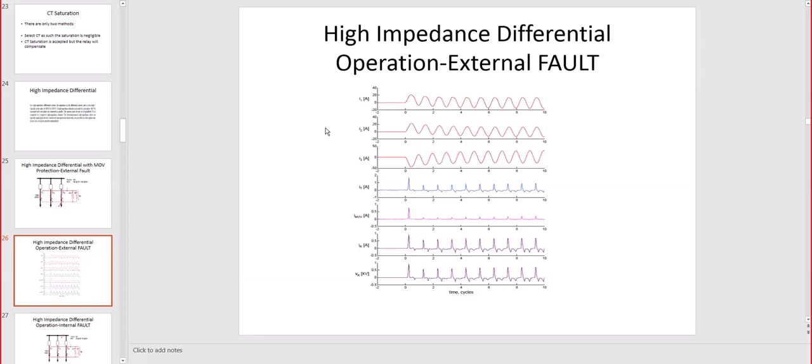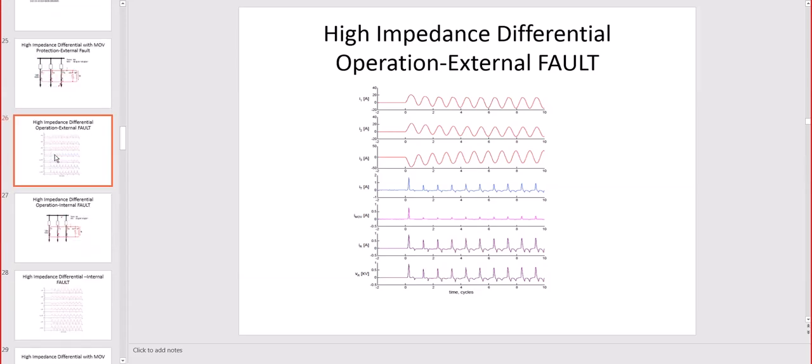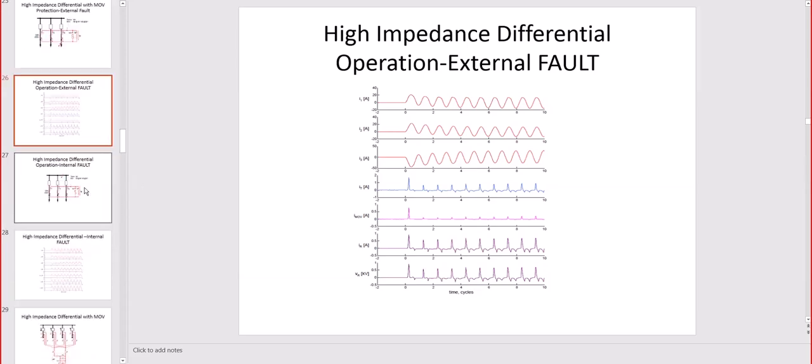Harmonics 3I0 is what interests us, and those are multiple of 3, and yes, they are composed by harmonic 3 and multiple of 3, like 6, 9 and so on, but really those are the ones that change direction as we showed, and they are the ones that cause trouble between the neutral and ground, let's say, of a transformer. It can even burn out the neutral to ground link if it's not protected properly, even though you have a cross section equal with the phase.